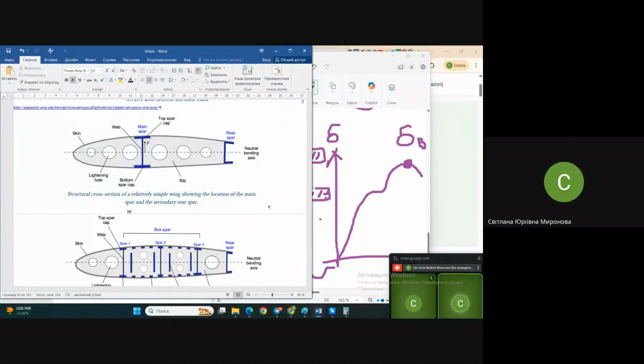The same thing may be said about the wing, but the wing, in contrast to the fuselage, has other names for these types of structure. Look, what is longeron structure, or spar-type structure of the wing? It's represented in the top picture. You see only ribs, which are responsible for keeping the shape, and spars: main spar, rear spar. One is double T, another is C channel profile.